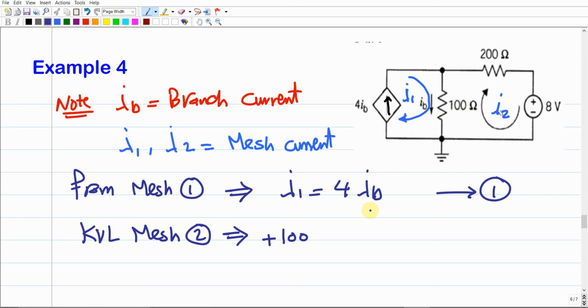I1, which one is going to be our reference? Our reference is going to be I2. So it means that it's going to be I2 negative I1. As forget about the IB. It's just a number and skip this number for now. Make sense? So it means that we have I2 negative I1. This should be the current over this branch. Make sense? So we got this current. We got this voltage over this element.